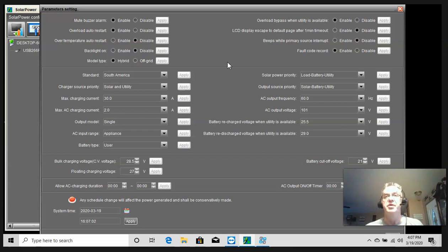So let's say your power goes out. This thing wires into all the electrical breakers within your breaker panel. It allows you, on your secondary panel, to flip those up. When you flip those up, you're running off battery power or off the inverter itself if you've got enough sun. So you probably would want a battery. For the circuits that you wire in, it's got two wires. One goes into the breaker in the main panel. The other gets wired together with the actual circuit going to the outlets, the refrigerator, whatever.